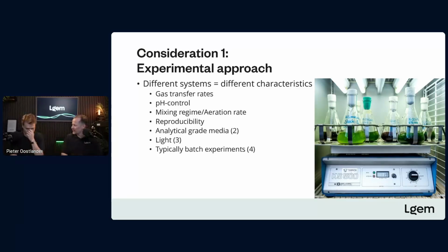Yes, to add to that, during my PhD, I indeed experienced when doing some bottle experiments that a small difference in the aeration rate or the mixing rate could cause a factor 2 to 4-fold difference in the biomass concentration obtained between duplicates. And this shows it's a simple, non-controlled system for some basic research or finding directions, but maybe it's not the right tool to develop your process.